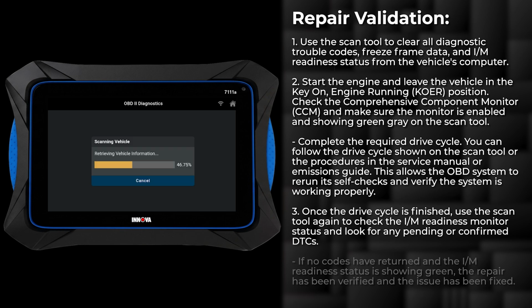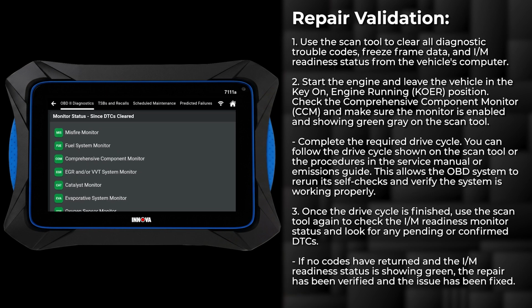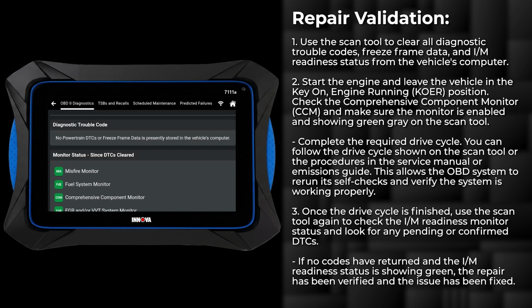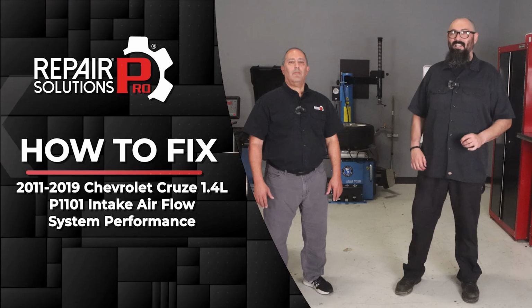Once the drive cycle is finished, use the scan tool to check the I&M readiness monitor status and look for any pending or confirmed trouble codes. If no codes return and the readiness monitor shows complete, which is green, the repair has been verified and the issue is fixed. This concludes the entire process for fixing P1101.